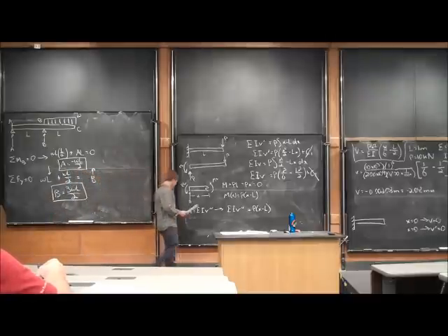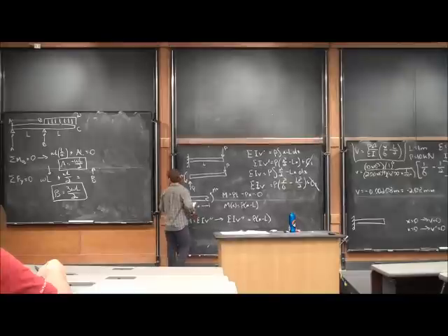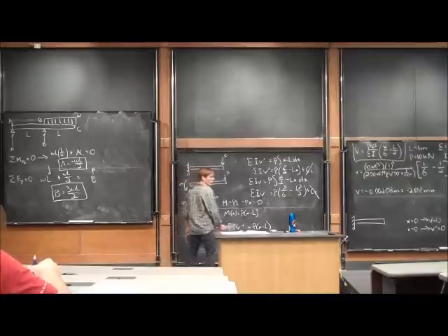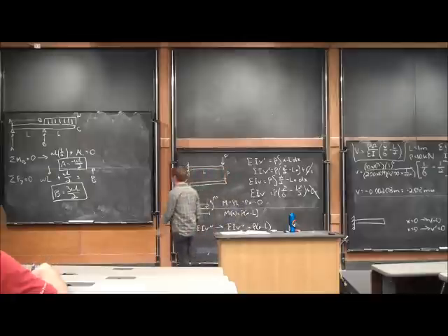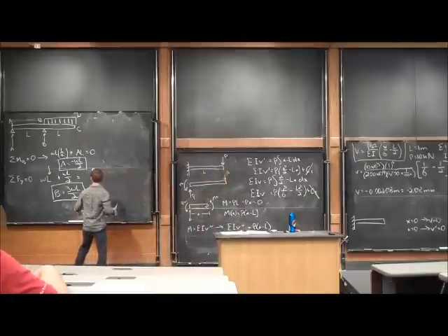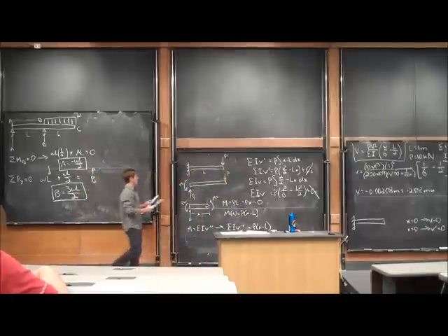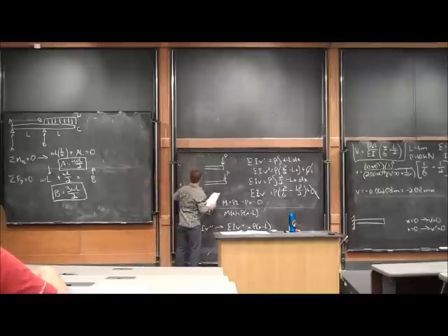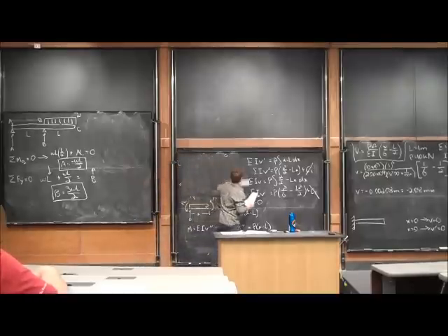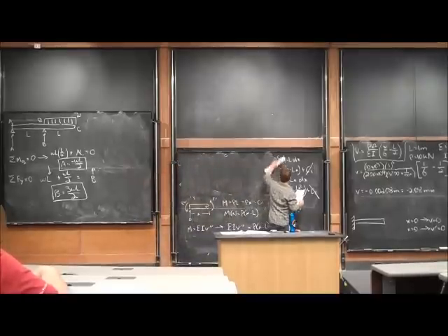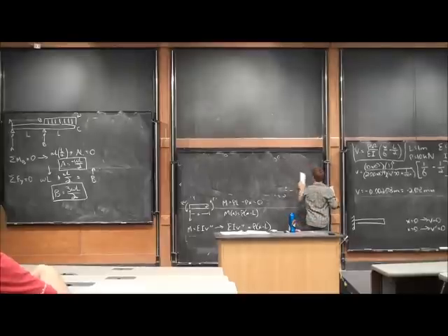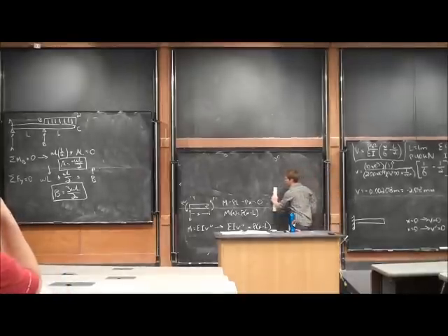Okay, so in this case, how many different sections do I have to look at? I have to look at 2, based on what my loading condition is and where my pins are placed. That means I'm going to have 2 moment equations that I've got to solve, which means I'm going to have two deflection equations, which I need to apply boundary conditions to in order to solve the deflection of the total beam.